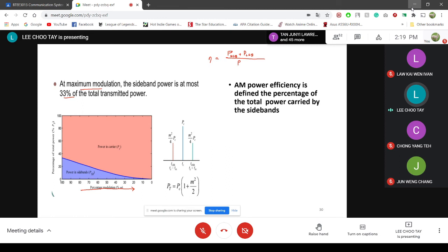So I have two signals coming up. One is the original version of the message multiplied with the original version of my carrier signal. On the other branch, I have the product of the phase shifted version of the message and the phase shifted version of the carrier signal. So what I do next is I either add them or subtract them, depending on which sideband I want to transmit.